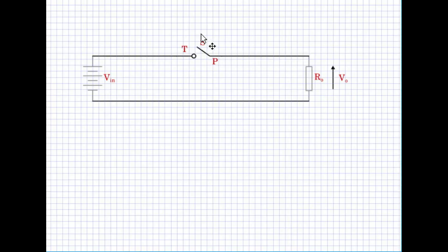This is not a recommended way of drawing the switch. We have to replace this switch with a single pole double throw switch, where there are two throws and both the throws are connected to well-defined potentials. In such a case, the pole, whether it is connected to one throw or the other, will have a defined potential and therefore the output V0.